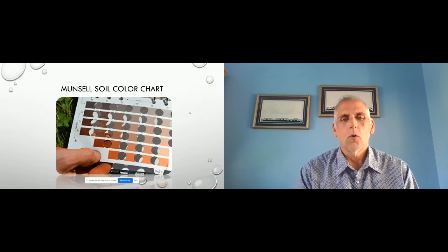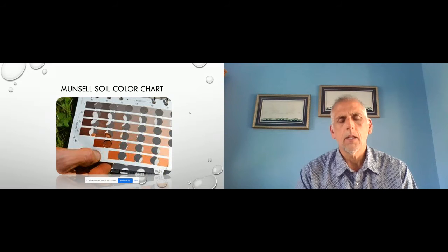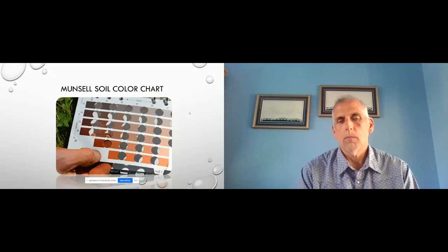We now look at the soil with the Munsell soil color chart. We're looking for things that are redoximorphic, which means that they are reduced and oxidized. So you may have really red colors, you may have really light colors. When you're looking at a soil and it has these gray colors in it, a lot of times what's happened is the iron has been depleted and moved to a different location. The natural color of the soil is not red. The natural soil color is white, gray, or blue. And the red comes from the iron. So it's basically just a rust on top of the soil particle.